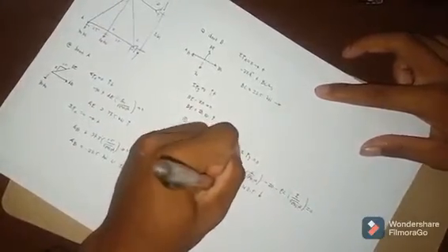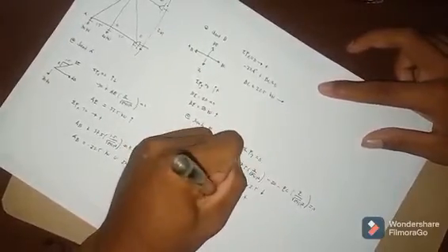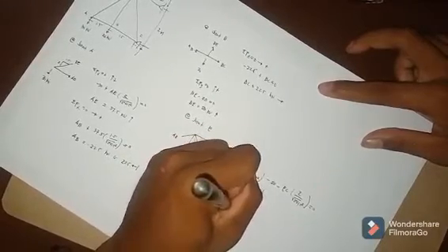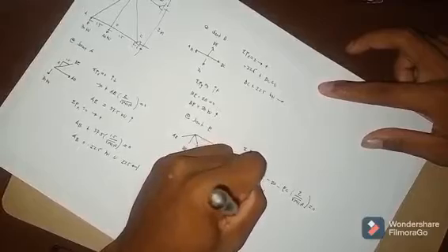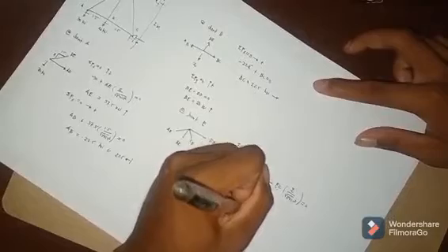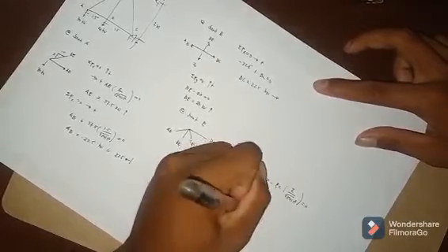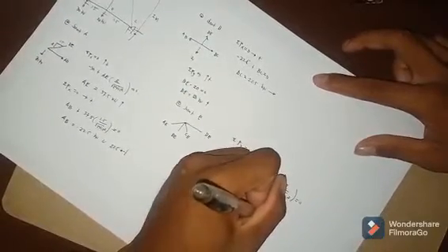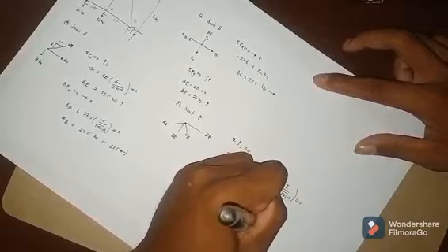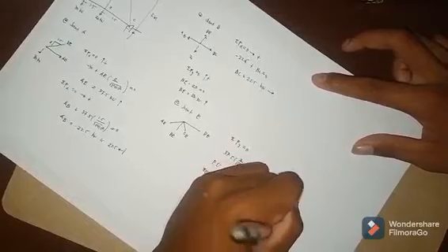So summation of forces na naman tayo, horizontal is equal to 0, and all to the right positive. So negative 37.5 yung horizontal ng AE natin times 1.5 over square root of 2 squared plus 1.5 squared, plus yung AC natin, which is negative 62.5, times its sine or vertical, so 1.5 over square root of 2 squared plus 1.5 squared, plus yung ED natin.